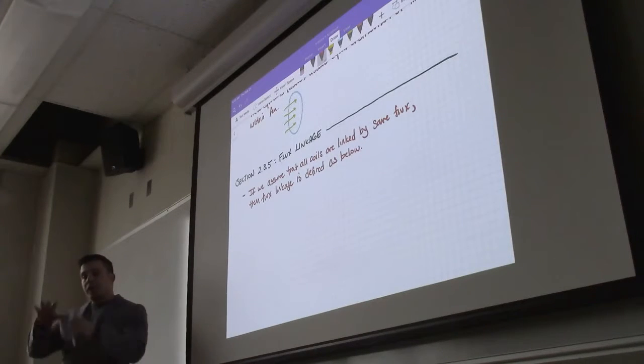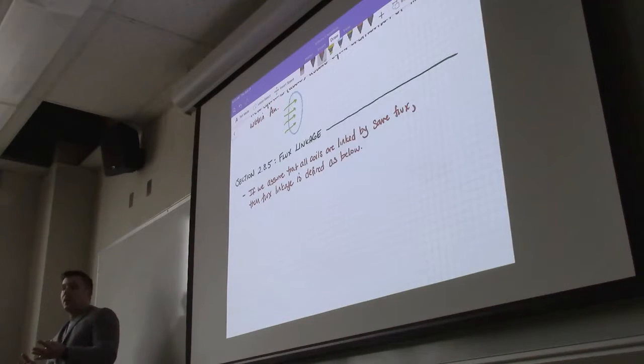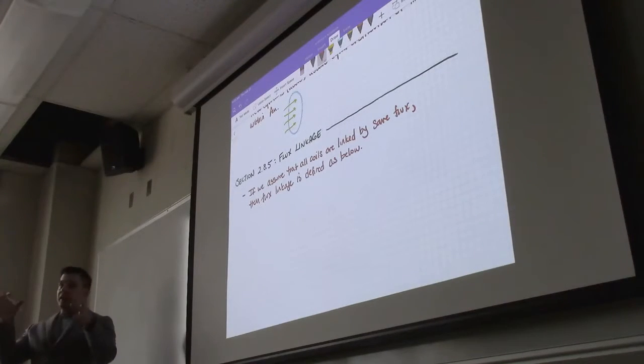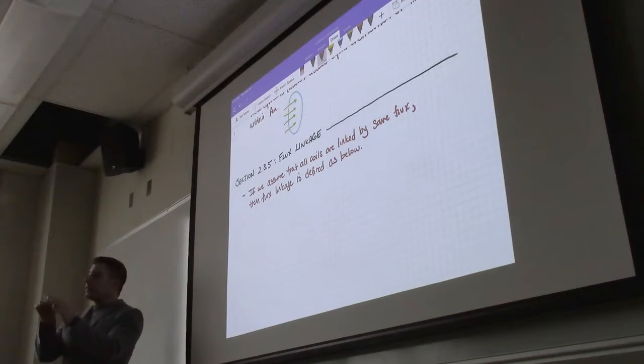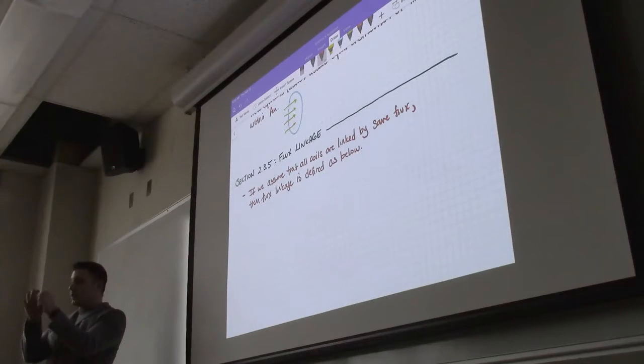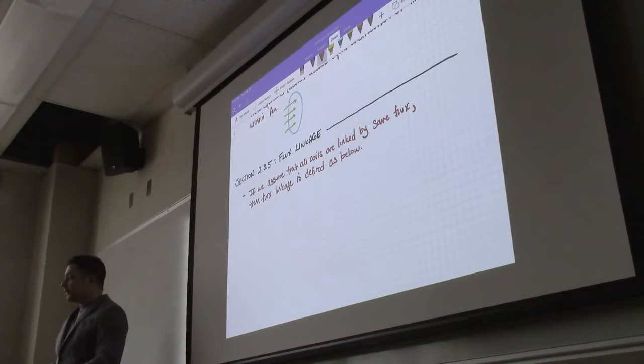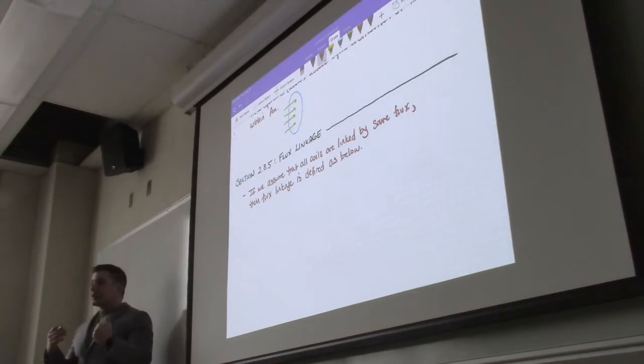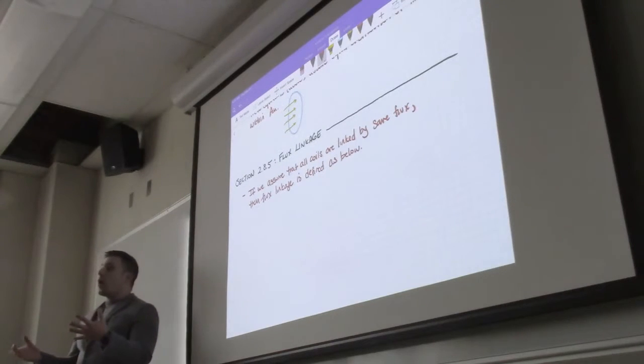So when they're evenly spaced, and we assume that the flux is flowing uniformly throughout the core, right? It's a lot like how we deal with the mutual inductances for the transmission lines. We assume, right, that because we have a symmetrical design, the effect of one on all the others is the same as their collective effect. You know what I'm saying? Like, you rotating it and looking at any individual coil, it's almost indistinguishable which one you're looking at, right? You look at the first coil, what does the rest of the system look like? You rotate it, look at this coil, what does the rest of the system look like? It always looks the same.